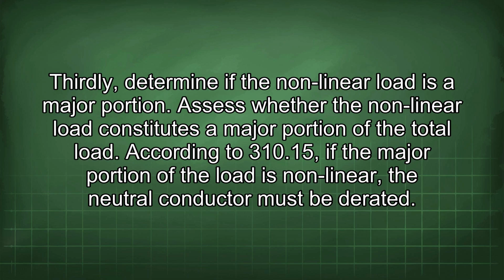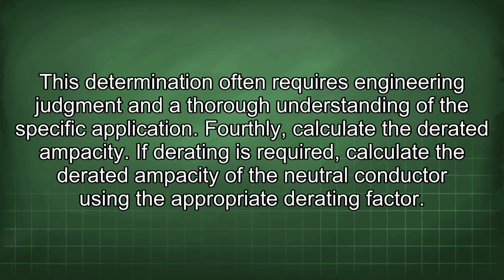According to 310.15, if the major portion of the load is nonlinear, the neutral conductor must be derated. This determination often requires engineering judgment and a thorough understanding of the specific application. Fourthly, calculate the derated ampacity. If derating is required, calculate the derated ampacity of the neutral conductor using the appropriate derating factor.